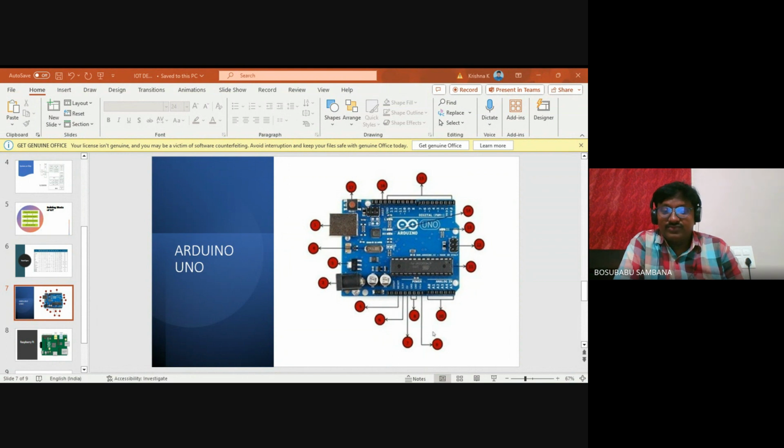Next, select upload from the context menu. If you give it a second, the board's RX and TX LEDs will begin flashing. Then "Done uploading" will be displayed in the status bar upon successful completion of the upload.